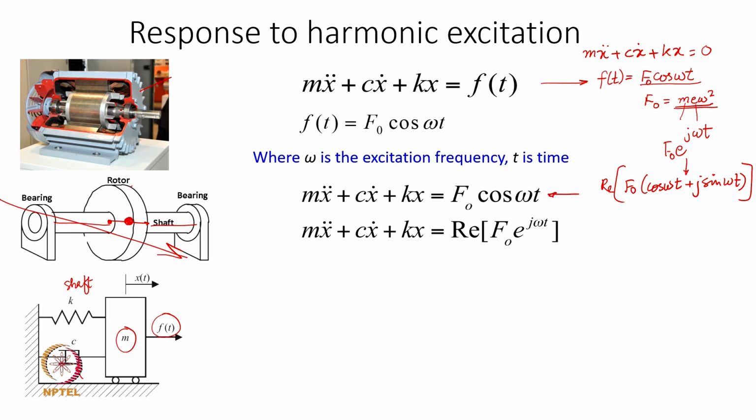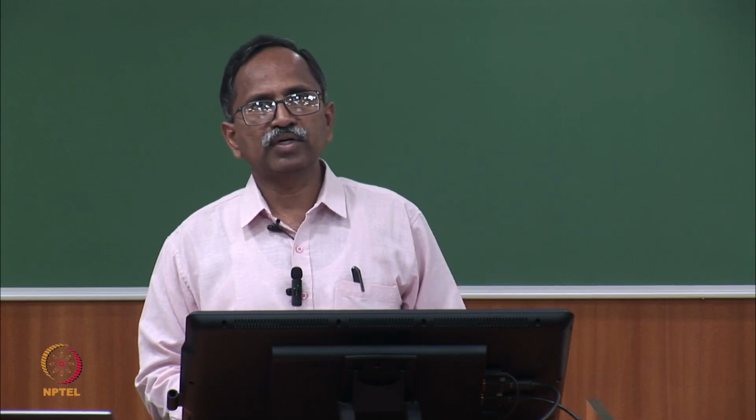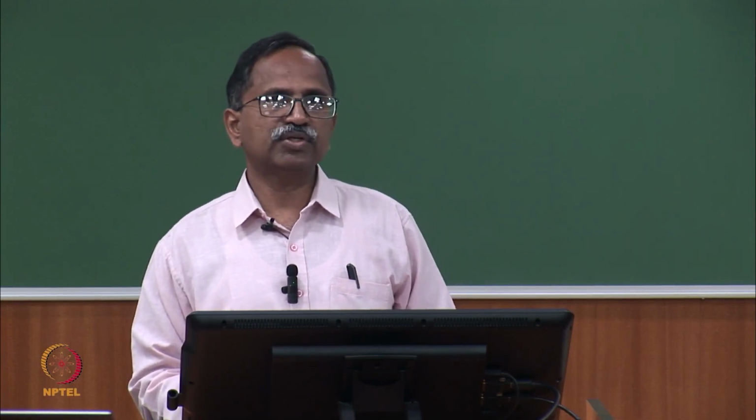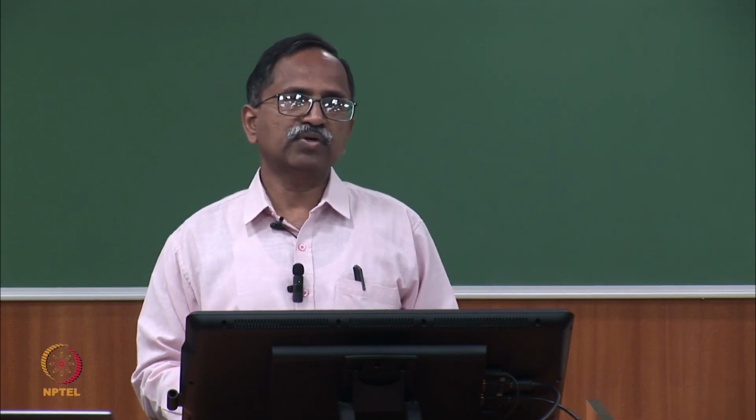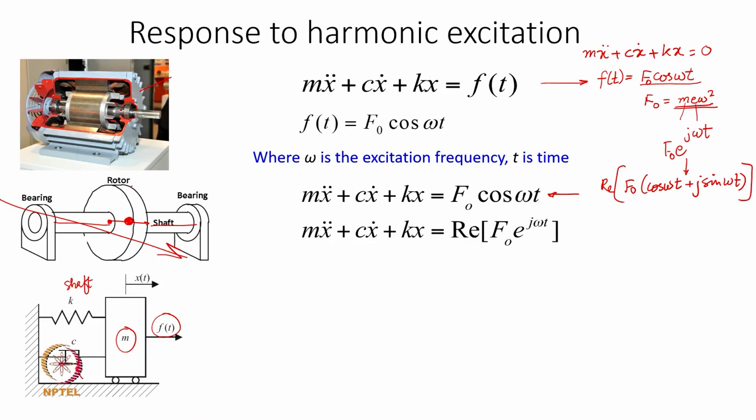Before we do that, there is a small assumption involved here, as we have already discussed: most of our vibratory systems vibrate with small amplitude of vibration. So we assume small amplitudes of vibration, and it also has implication in another assumption, that the system is linear.